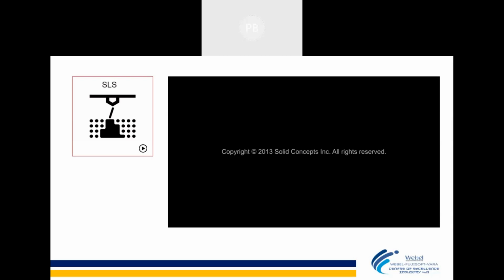Because after seeing the video, the product is going into the powder bed, so we are putting the next layer on top of the previous layer. Right. Even where there is a hinge portion, the powder itself is going to support the product, as it is surrounding it from all sides. Yes. So powder is acting as a support material in the case of SLS technology. So powder is always acting as a support material.